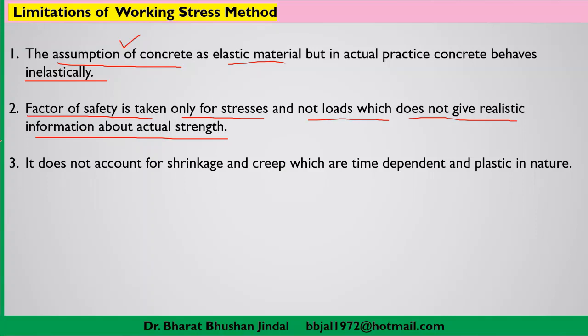The third limitation is that in the working stress method we don't discuss anything about shrinkage and creep. So far, the working stress method does not clearly indicate what provisions we have taken for concrete when it is subjected to loading and when shrinkage and creep stresses develop. We have discussed that shrinkage and creep stresses are also time dependent and plastic in nature. So the working stress method is silent about the stresses which may develop due to shrinkage and creep.